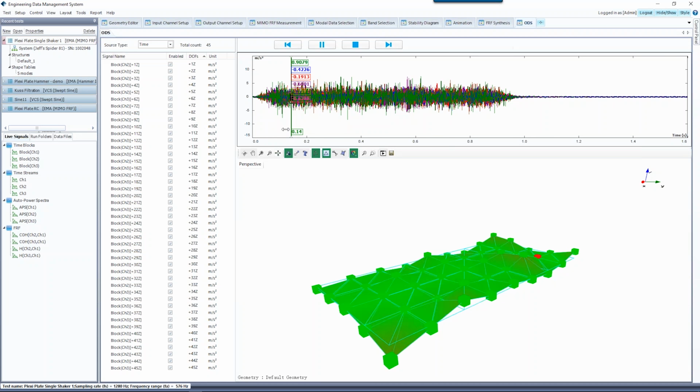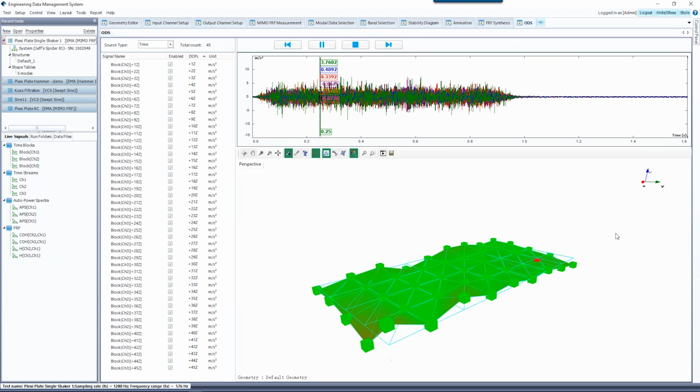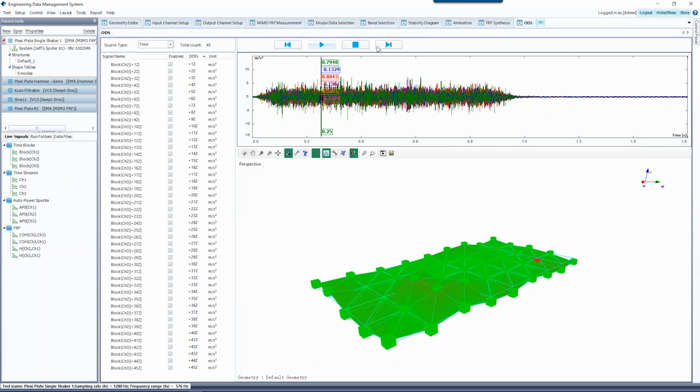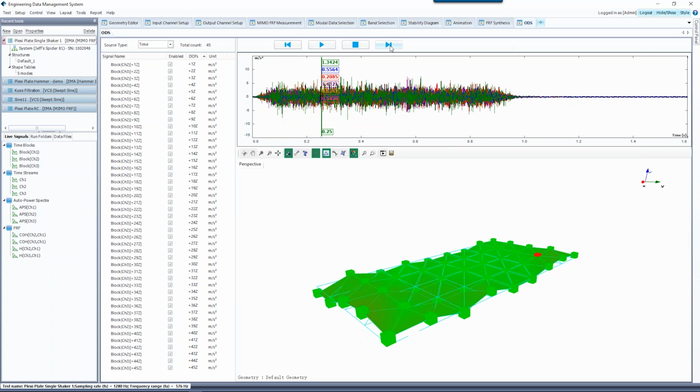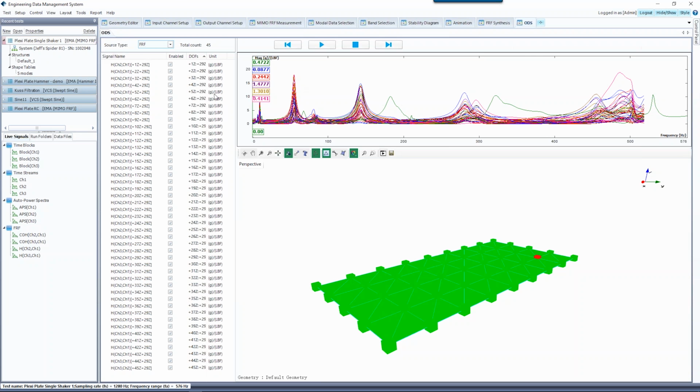So it's point to next, just doing that. This is the time domain, and we can also look at the frequency domain. For this case, we suppose this is the FRF. Let's just drag it to here, at this point. If you look at the structure, it rotates along the x-axis. So this is one rigid body mode at low frequency.